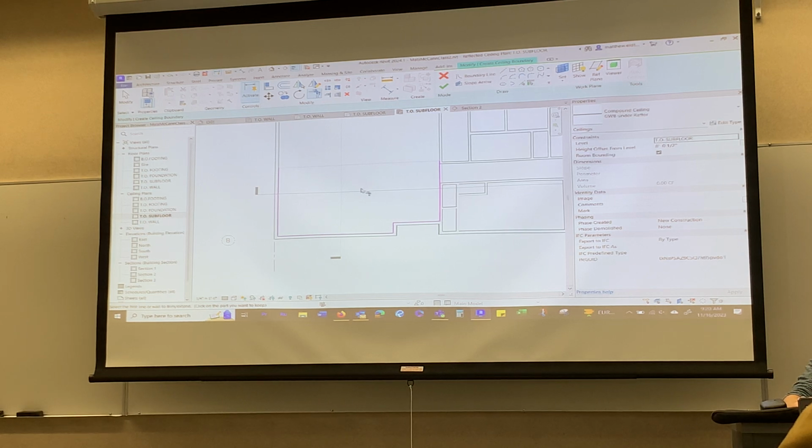If I were to go look at it, this section right now, it's looking like this. Okay? The side we just drew is still flat, and the other side is up there. So that means I have to make it the same. So while I'm still in edit, modify, create ceiling, sketch mode, I'm gonna click slope arrow, and I'm gonna draw one in here. It doesn't have to be in the center. I'm just gonna pick this line and come in here until it snaps.